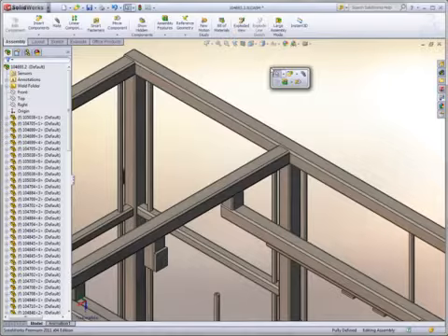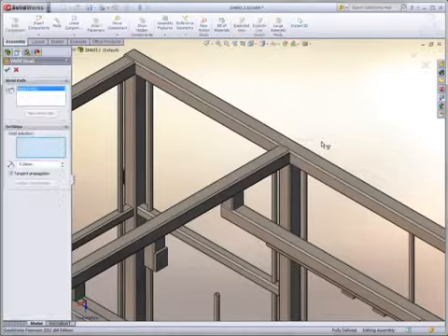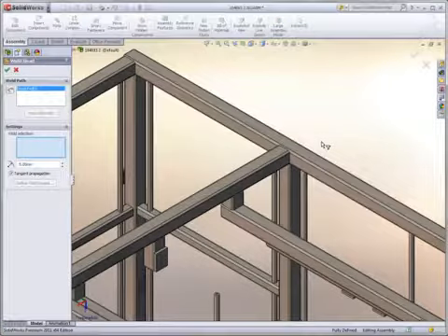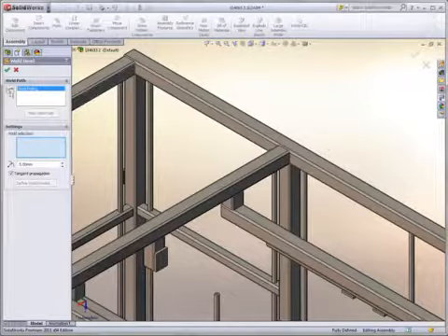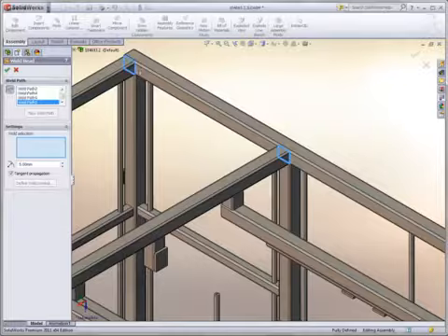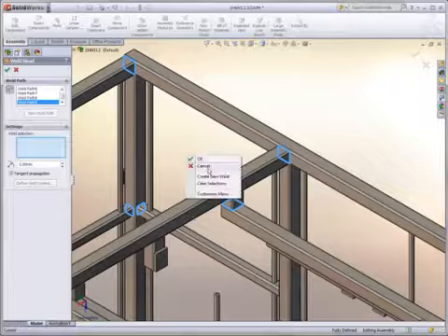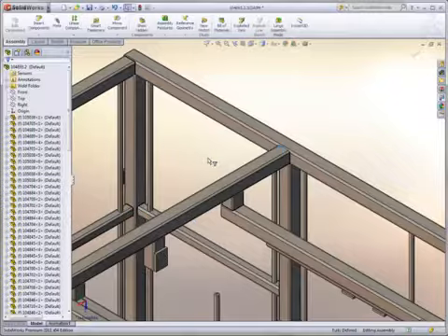When working with complex welded frames, you might need to create a significant number of welds. To tackle these cases, the Weld Bead tool has one last powerful capability: the new Smart Weld Selection tool. Once enabled, all you have to do is swipe your cursor across the parts to be welded together. The selection tool automatically finds the appropriate choice and creates multiple welds at once. It's extremely fast and easy.